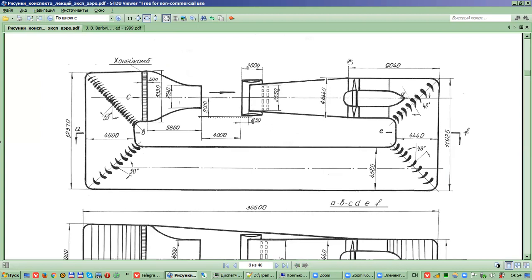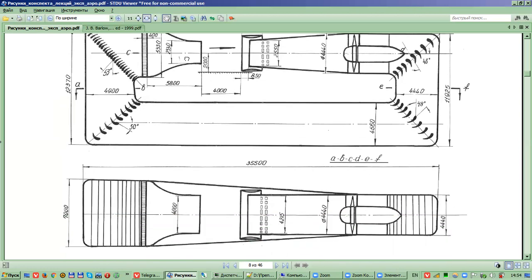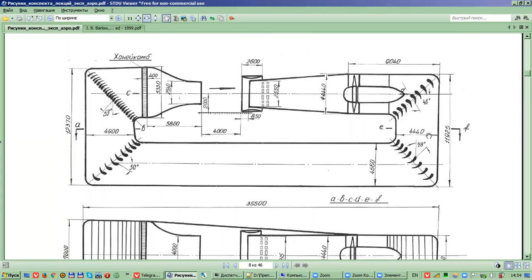After this we have the diffuser. The diffuser has a small ratio, the airflow expands in the diffuser, so speed goes down, and this is for better efficiency of the propulsor, the propeller. So in the contraction section, we have increasing speed to the desired level, and in the diffuser we have decreasing of speed, so speed increases in this part and decreases in this part. After the propeller, you just have the return channel to the inlet.